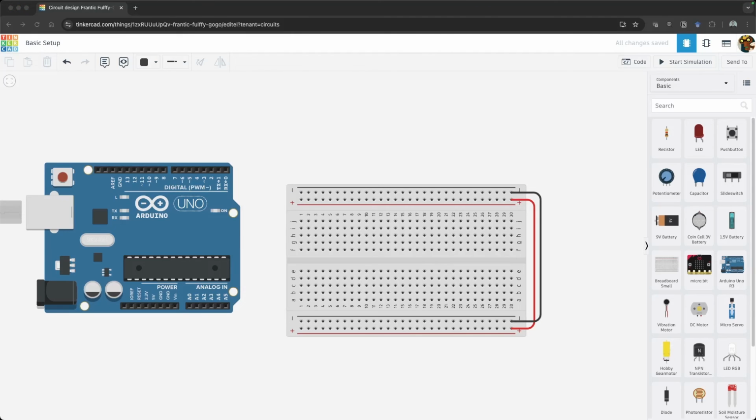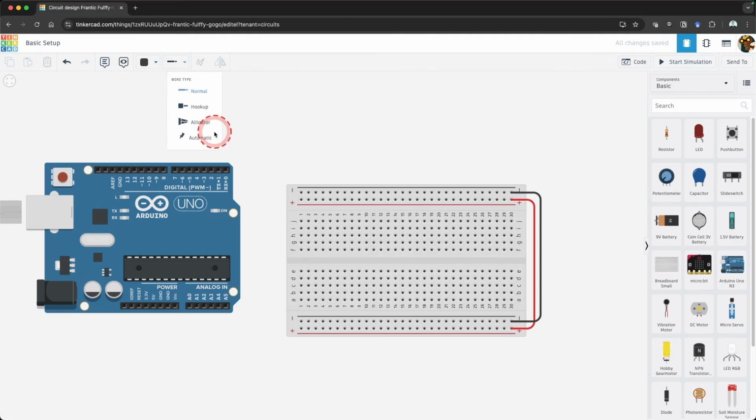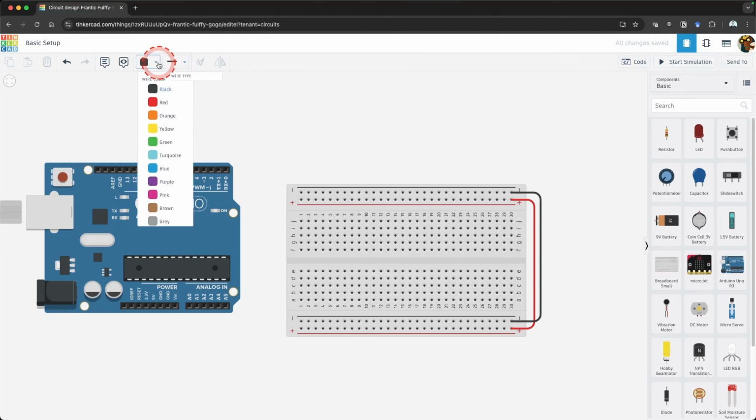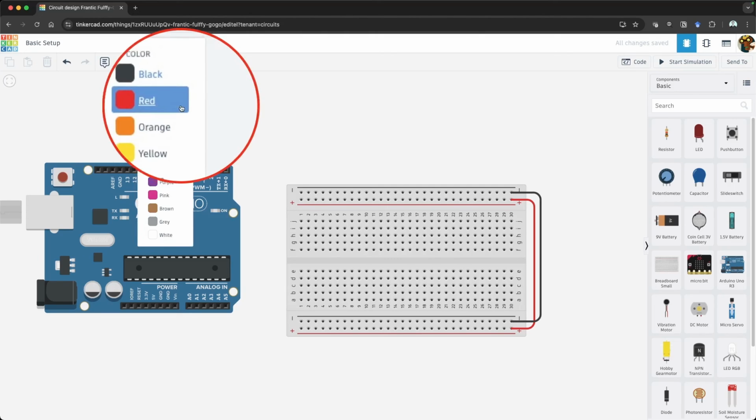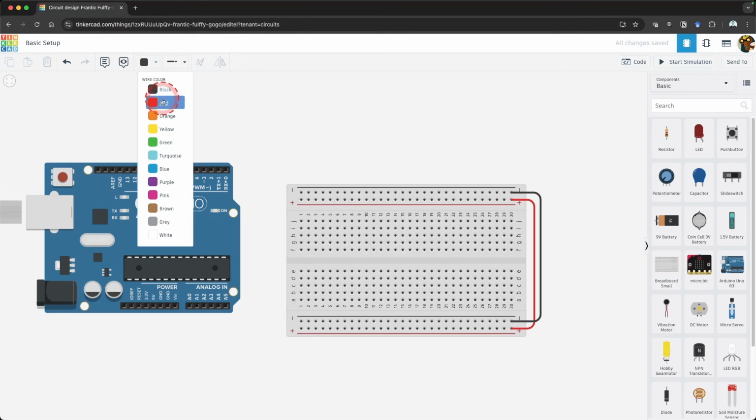This is a good time to talk about the wire in your kit and color coding. In short, the wire in your kit is all the same. There is no difference between a blue, orange, green, red, black, yellow, or purple colored wire. You can use any color wire to connect a component. With that in mind, you should use wire color as a visual indicator. It is a good idea to reserve red wire for the plus or power connections and black for negative or ground connections. This will help when your circuits become more complex.